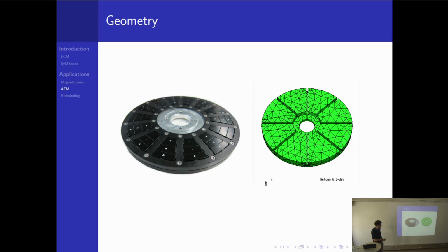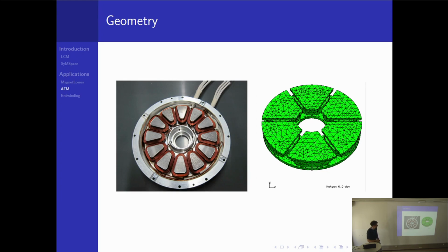So these parts are the magnets, and there we have the rotor yoke, and this is similar here. I mean, this is a bit of a different geometry, but I think you get the idea how the rotors for axial flux machines would look like. And a bit more complicated is the stator. So you see here the coils, and this stator has no flux collectors.